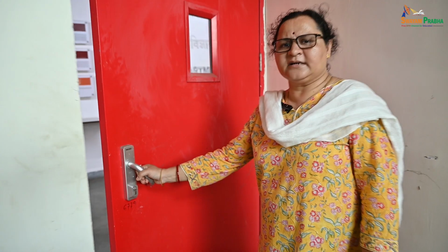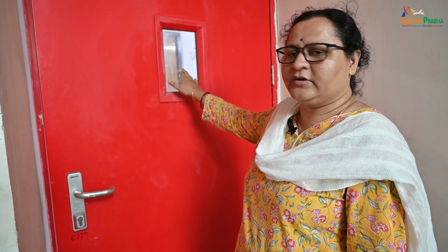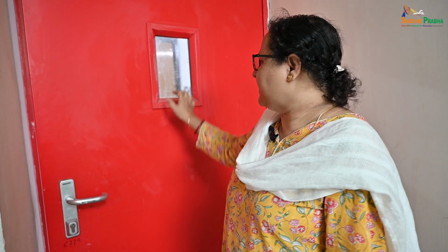This door is again a fire rated door, usually 2 hours fire rated as a mandatory requirement. It has to be installed in a fire check staircase. Here, fire rated means it will be 2 hour fire safe, also for this glass portion, so the entire assembly is fire rated. This glass is a tempered glass which can withstand high temperature. This allows visibility on the floor on fire, and lets you check whether this staircase block is safe or has less smoke inside it.